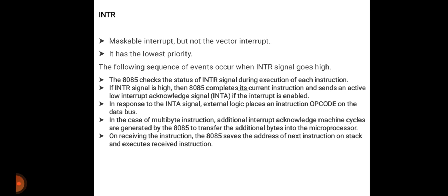In case of a multi-byte instruction, additional interrupt acknowledge machine cycles are generated by the 8085 to transfer the additional bytes into the microprocessor. Then, on receiving the instruction, the 8085 saves the address of the next instruction on the stack and executes the received instruction. This is all about the INTR signal.